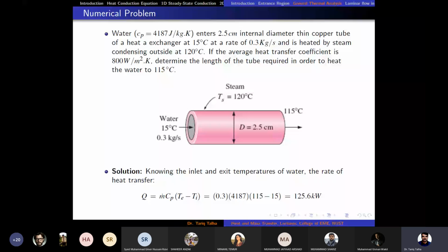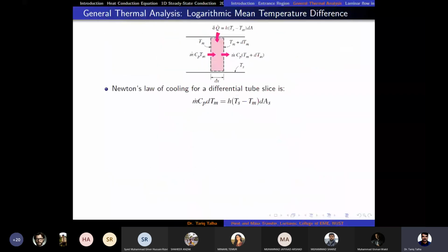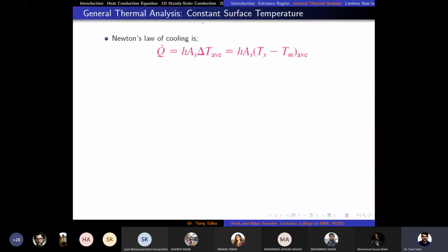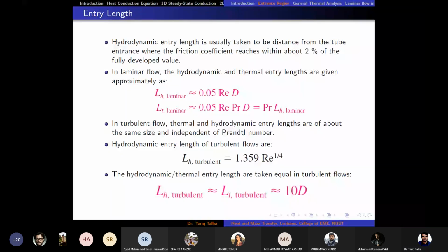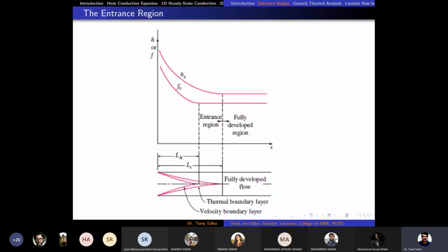So first of all, we would go through the derivation for the Nusselt number, because if you remember, if we talk about laminar fully developed flow, the H value becomes constant in the fully developed region, so we can expect a constant value of Nusselt number for fully developed laminar flow, for the constant surface temperature boundary condition and the constant surface heat flux boundary condition.